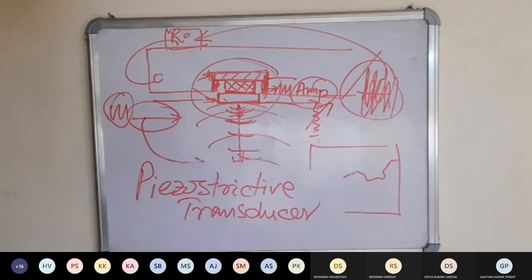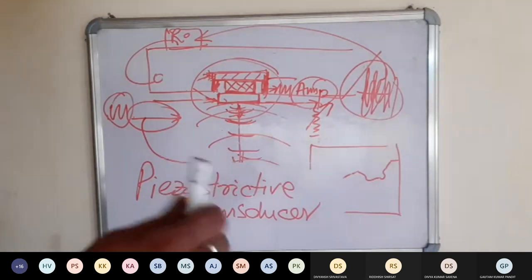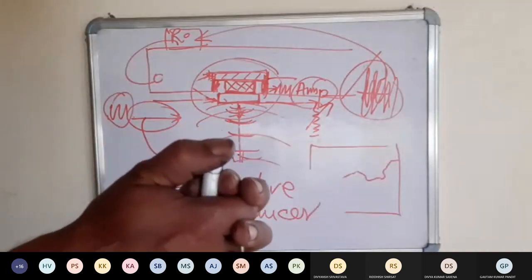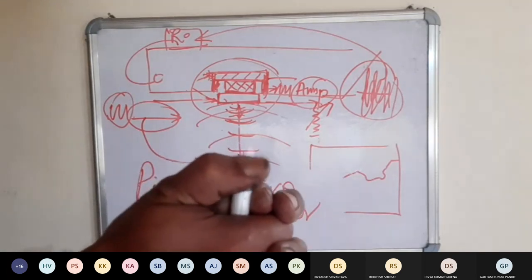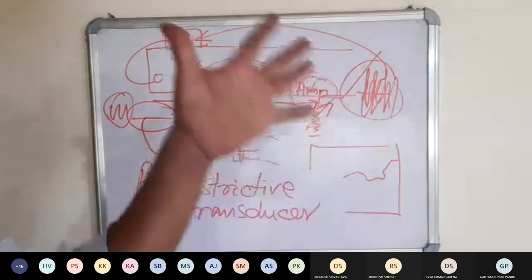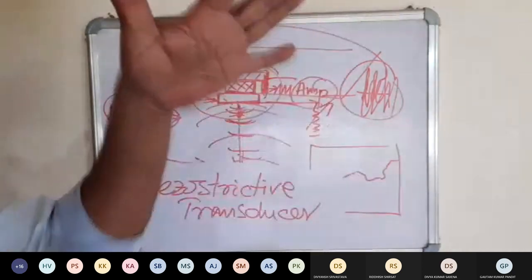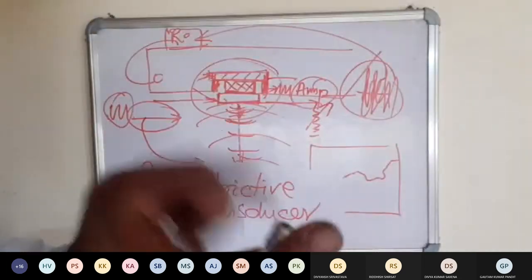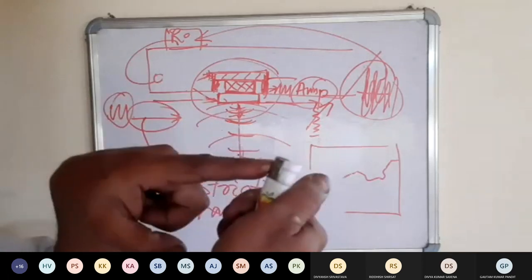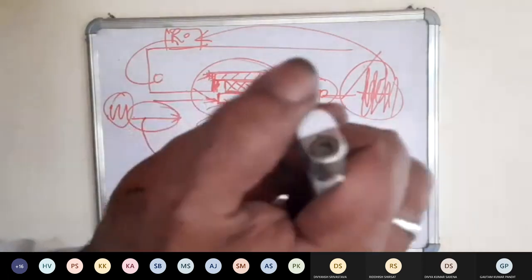There are normal cigarette lighters that you have. They are also using the same principle, the piezoelectric effect only. Say, for example, if this is the lighter, when we are pressing it, there is a spring load, और स्प्रिंग लोड के बाद जब क्लिक करते हैं तो एक टाइम के बाद रिलीज होता है. That means because of that spring load and locking system, there is a sharp knock on the piezoelectric element here. There is a crystal inside this, and that produces the spark.